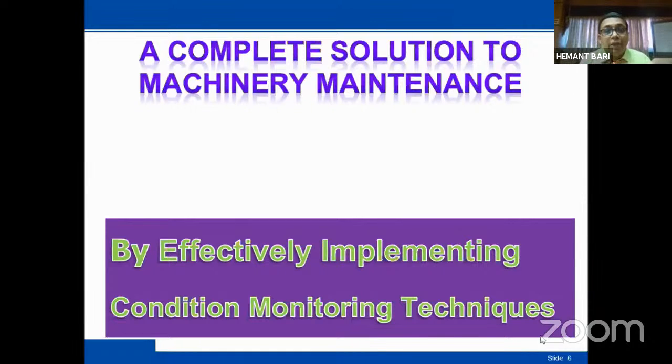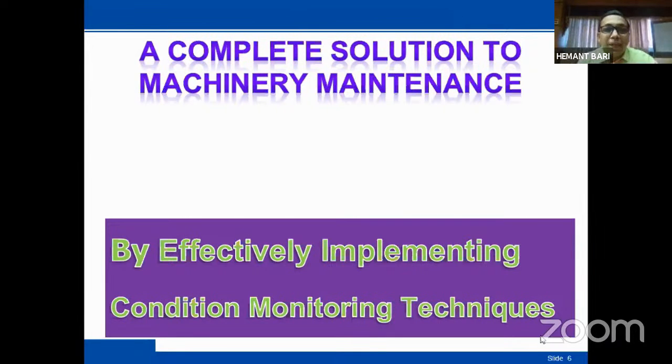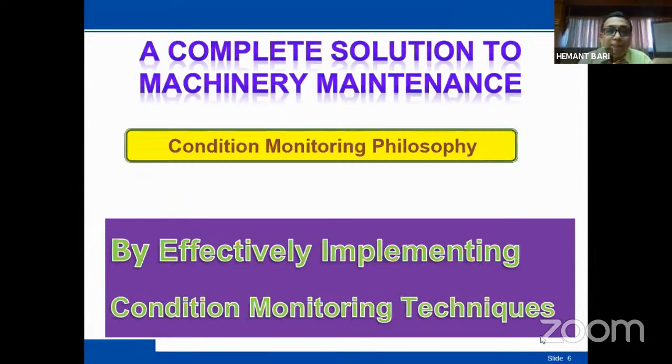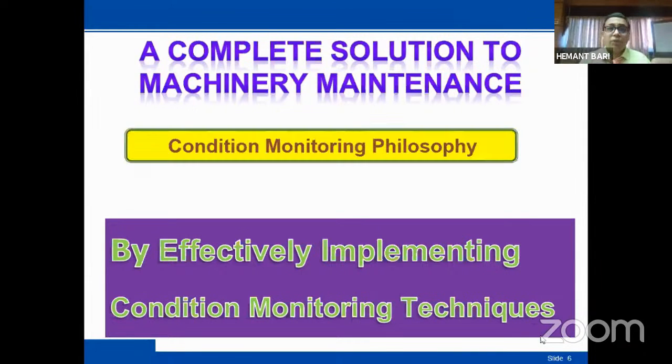Similarly, for the machines also, a lot of condition monitoring techniques are available, but looking at the symptoms, which parameter deviated: if my vibration has increased, then I will take phase; if my temperature has increased, then I will do thermography; if there is noise from my gearbox, I will go for oil analysis and such kind of things. Okay, so looking at the symptoms, you should select the appropriate test. Leg pain, you should go for an X-ray. Fever, go for a blood test. Okay, like that. So the data of all techniques is not necessary.